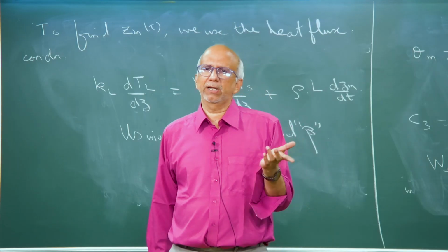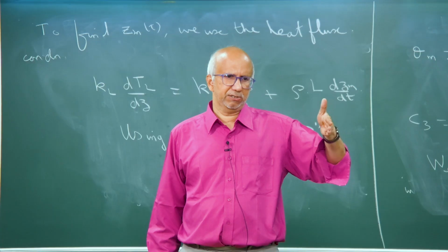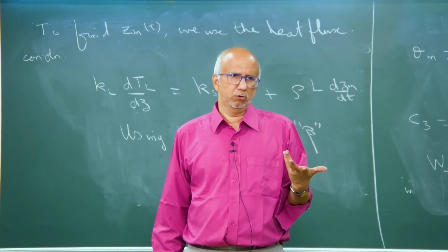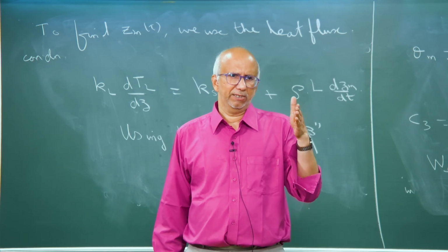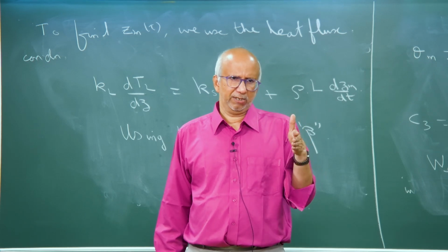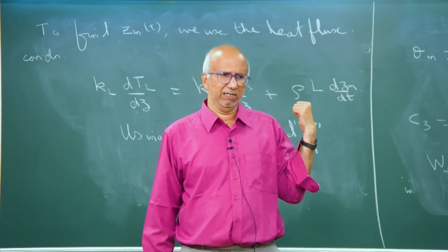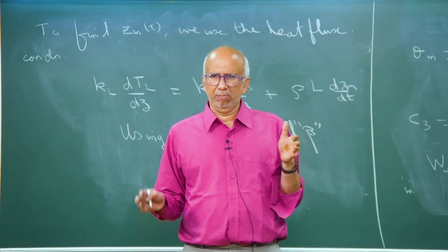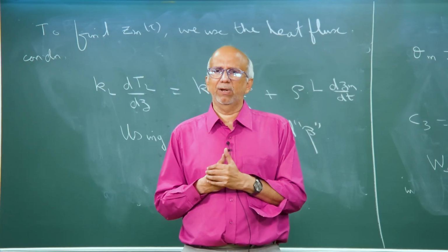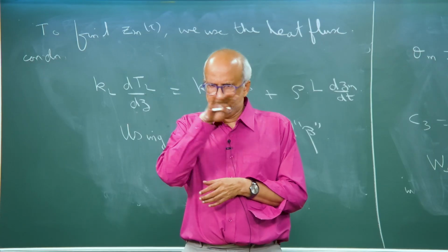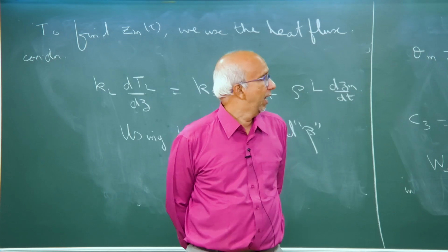So, when you do it numerically, under some limits you can match your numerical results. When you do it numerically also, you need to be confident that your numerical results are correct. So, under some assumptions the numerical results will collapse to the analytical solution we have got, okay, maybe very thin diameter of the pipe, for example, or very high thermal conductivity, I can say the cross sectional temperature is uniform. So, those kinds of things we can do and verify.